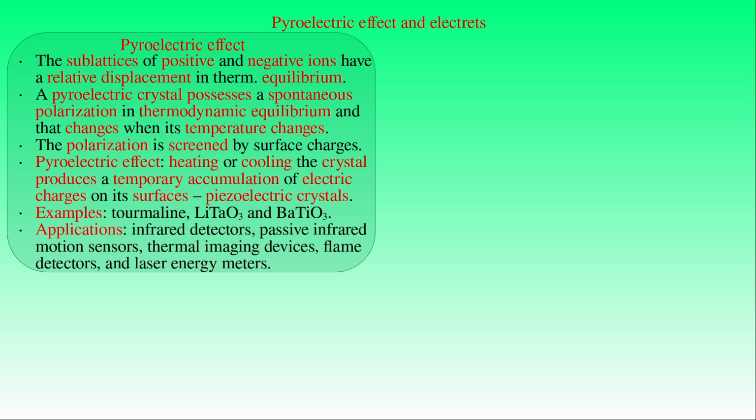Pyroelectric crystals are widely used in infrared detectors, where changes in the incident infrared radiation produce temperature variations that alter the crystal's spontaneous polarization, generating an electrical signal proportional to the radiation intensity. They are also applied in passive infrared motion sensors, where changes in the infrared radiation emitted by moving objects produce temperature variations in the crystal, generating electrical signals that indicate motion.